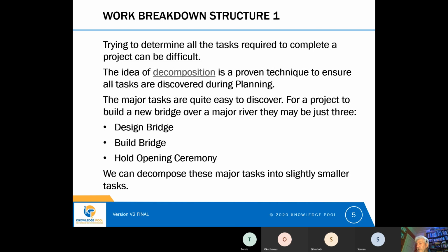And as I mentioned, the engineers who built the great infrastructure projects, like the railways, would have taken exactly this approach. They would have broken the task down into surveying the route, then analysing all the materials that they needed, and then starting to build the tunnels and the embankments that they need, and then laying what they call the permanent way, which is the railway lines that go on top. So they would have followed exactly this process of identifying the major tasks and then breaking that down so that they would have a task to build the first bridge, the second bridge, the third bridge they need, the embankments, and only when the entire route is available would they then perhaps just start to build the track.